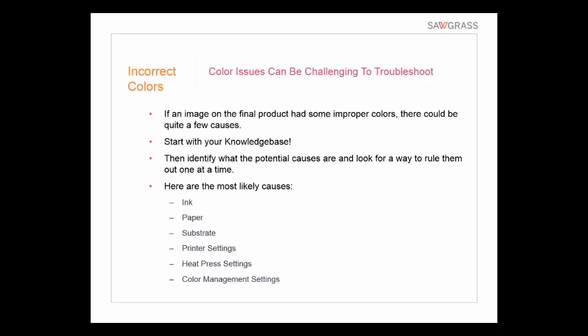Also pay attention, if this is a new substrate, it may have different settings. We get used to it being 400 degrees, medium pressure, for 1 minute, but that's not what you apply in every situation. So pay close attention, especially if you go into ceramics. Anything ceramic, we have to do for a longer period of time. So you do want to pay attention to that.